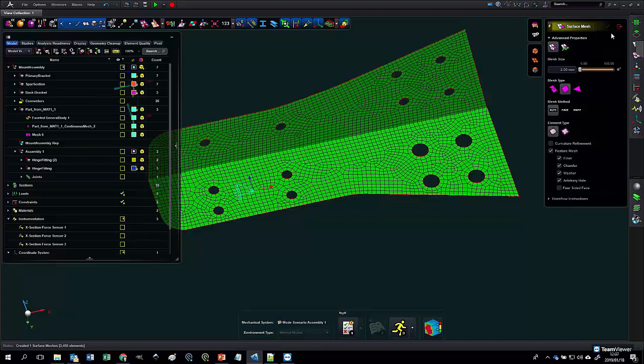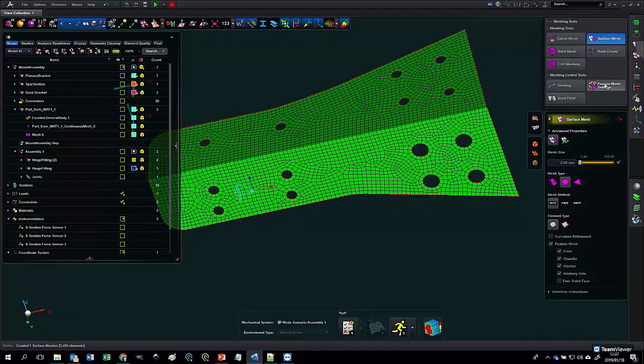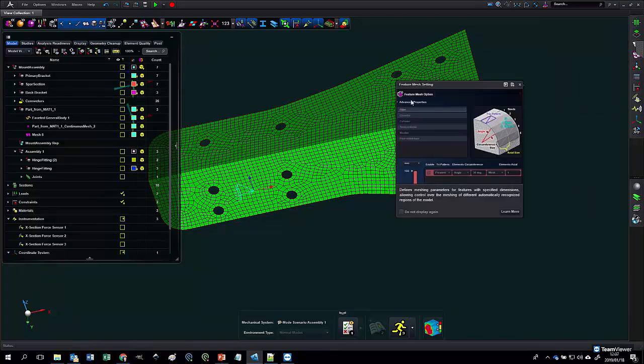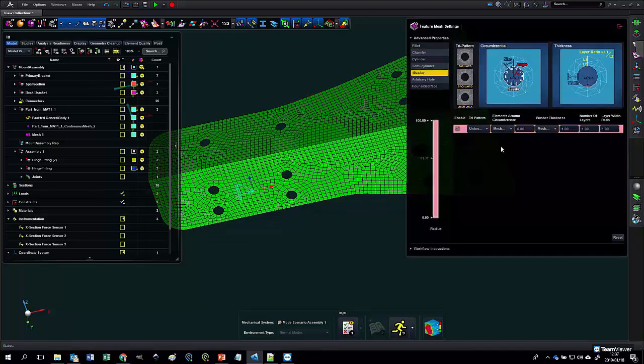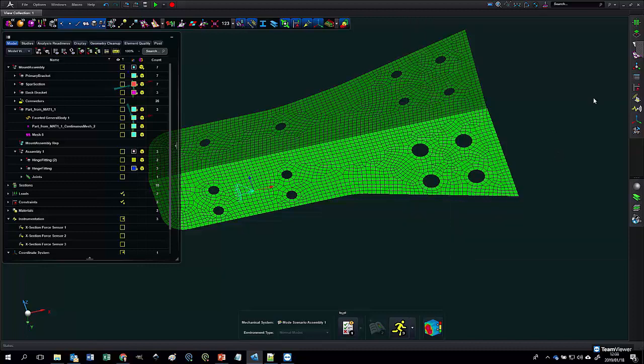And in fact there were some mesh settings defined for washers over here. If we go to the washer settings, in Apex you have this ability to set up different rules in the way washers should be handled, and you can even subdivide them and have different rules for different groupings.